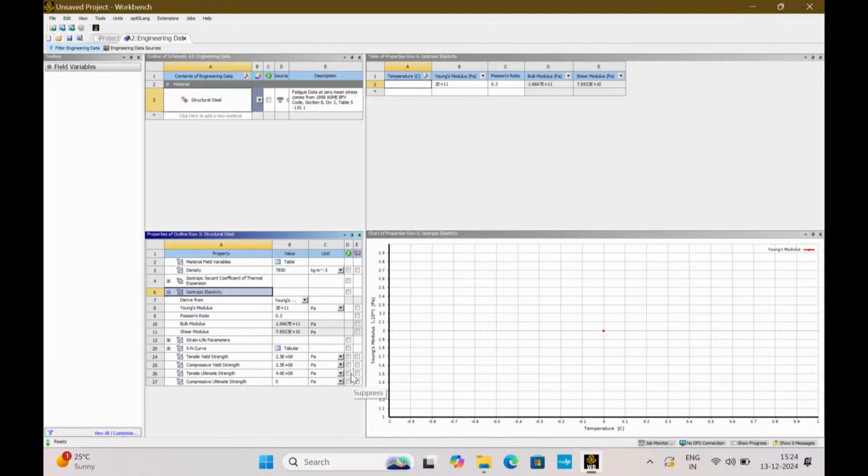So today in the class Suman sir showed in the presentation, he has taken 500 kilopascal. So that same Young's modulus we will be prescribing over here. In a real physiological scenario it varies from around 300 kilopascal to around 2800 kilopascal, in that range. Exact range I am not sure, but in that range. So for the time being you just take 500 kilopascal, so 500,000.